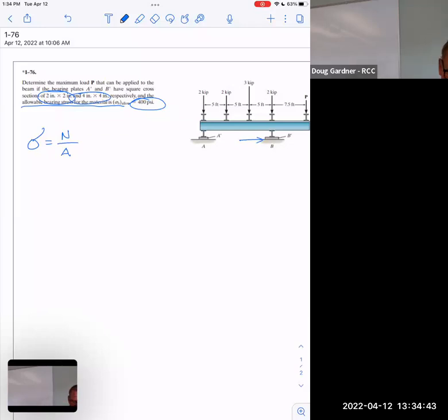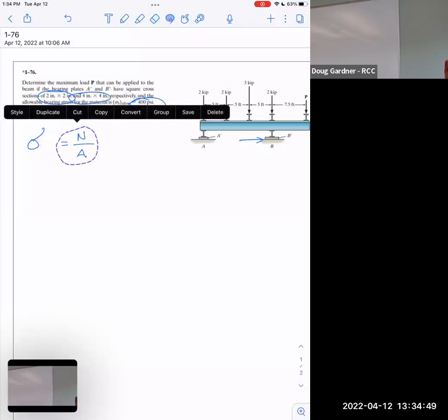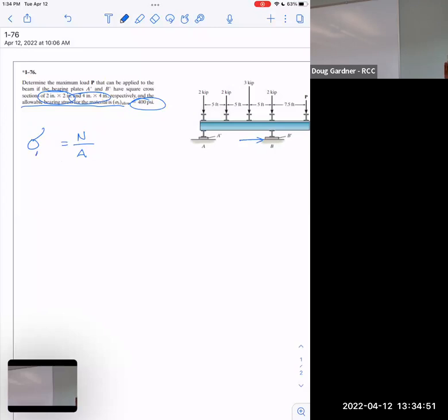And so in this section, really what we're just talking about is instead of just calling that sigma, we're thinking of that as the allowable number. And we've been given that. We were told that that's 400. So we know that's 400. And I find myself wanting to stick the units into that all the time, and sometimes even writing pounds per square inch instead of PSI, so that I know the other side, whatever I do over there, has got to result in the same units.